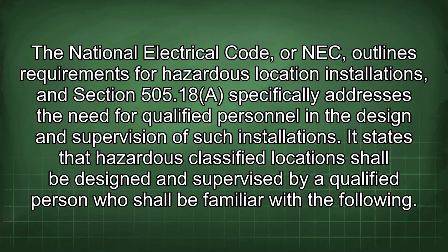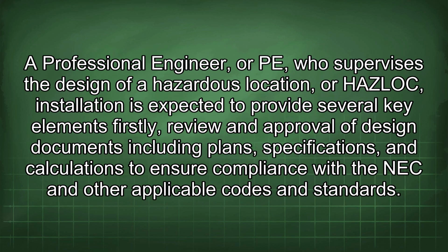The National Electrical Code, or NEC, outlines requirements for hazardous location installations, and Section 505.18 specifically addresses the need for qualified personnel in the design and supervision of such installations. It states that hazardous classified locations shall be designed and supervised by a qualified person who shall be familiar with the following: a professional engineer, or PE, who supervises the design of a hazardous location, or HAZLOC, installation is expected to provide several key elements.